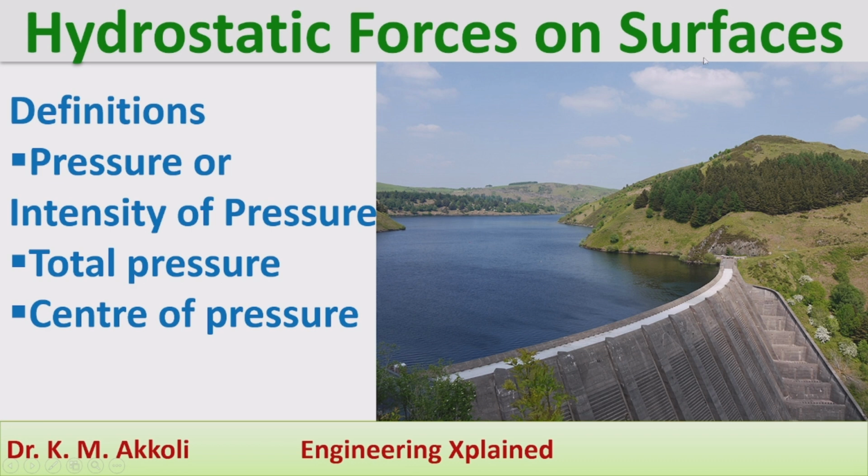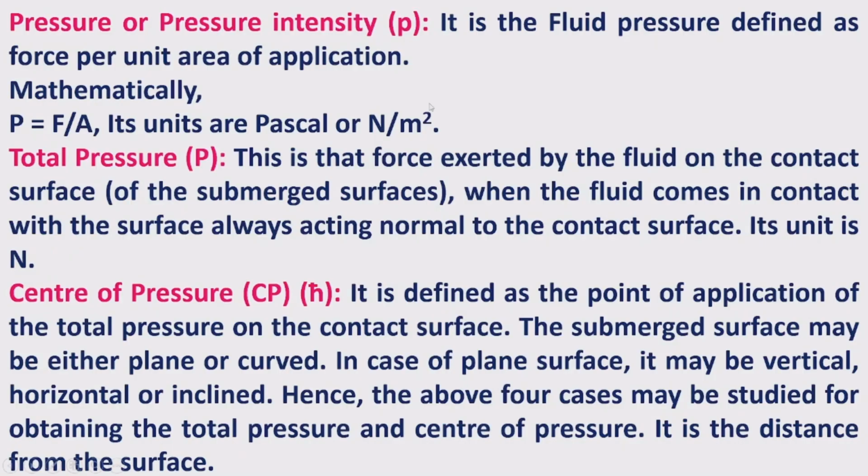And on the surfaces we are going to take, that means the submerged surfaces, what forces will be exerted by the fluid when that fluid is static, that we are going to discuss. In this I'll discuss the definitions concerned with hydrostatic forces: pressure or intensity of pressure, total pressure, and center of pressure. First I will take the definitions of these, and later we'll discuss how the forces act.